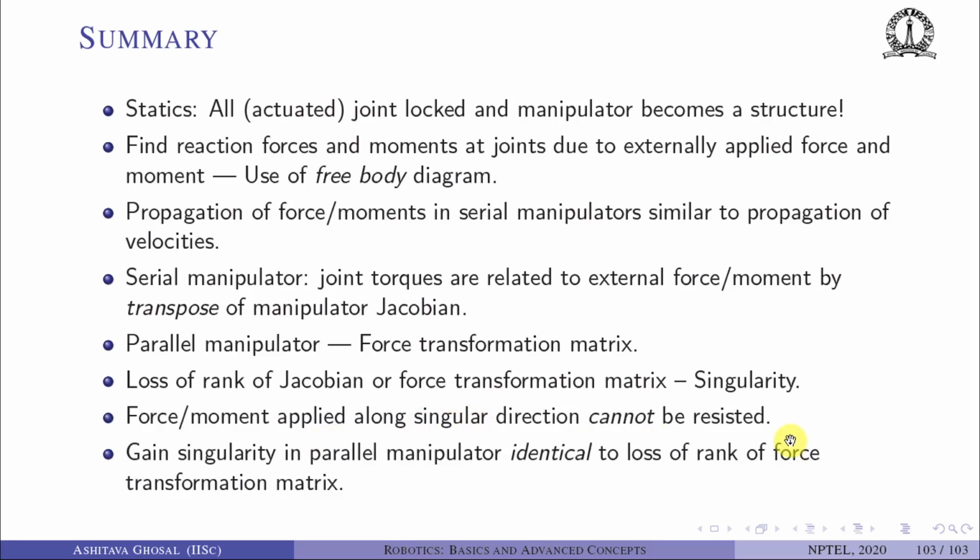And gain singularity in parallel manipulator is identical to the loss of rank of force transformation matrix. Okay. So determinant of H equal to 0, which is loss of rank of force transformation matrix, is same as determinant of K star equal to 0.